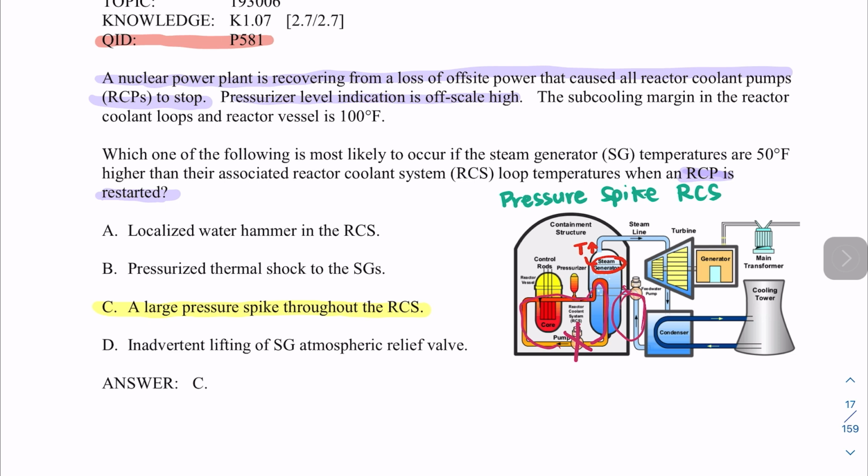It's like when we have a pipe system, we need to bend the pipe system, or we have condensation in a steam line. We need to vent it, we need to warm it, and we need to make sure that we don't have any condensate, because that's going to create this pressure spike. It's the same thing, but a real world example for a nuclear power plant.